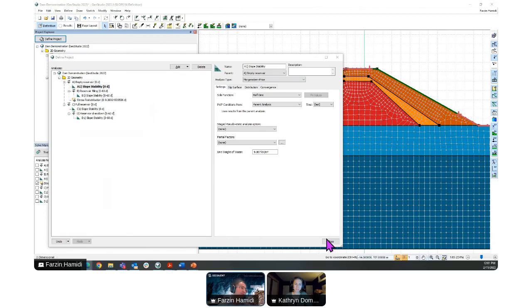I can say it this way: you run the model and do a trial and error. For example, for different locations where you have a piezometric line, try to find the best boundary condition that you can apply to your boundaries to get that piezometric location. But try not to put the piezometric location directly into the model, because it provides a fake boundary condition in the middle of a model, and maybe you will produce some extra flow into your model, which is not what you want to do. Is that a complete answer to it, Catherine? Do you want to add anything?